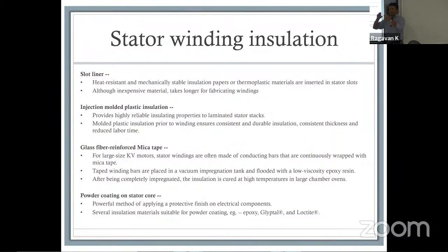You can have tape. So basically the idea is you design the whole thing and you insert it, right? So you're creating a nicely formed coil. You get the maximum compactness into it. It is wound around with mica tape and you put it in. So that's one way to do it. Then you impregnate that, and that allows your insulation to be cured, and that keeps the entire thing secure. You can also use this as a way to make sure your windings don't vibrate inside the housing, because that could be another source of noise.